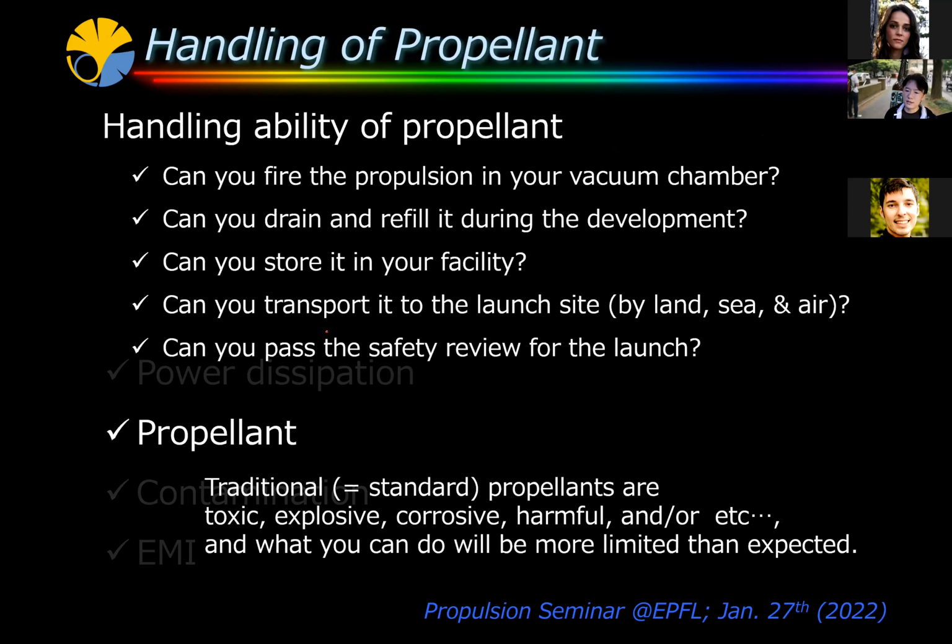And the second one, maybe the most important, is handling of propellant. The handling ability of the propellant becomes very important. Can you fire the propulsion system in your vacuum chamber? Usually during development, you want to check the status of the propulsion system, and you may want to fire it using your facility.